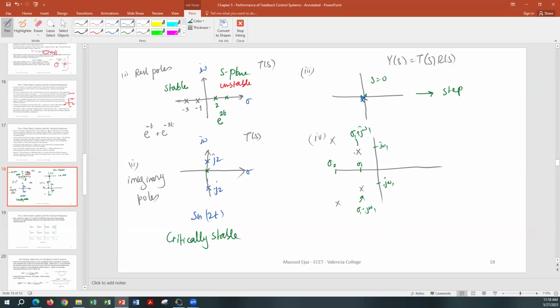As far as the effect of omega is concerned, the higher the value of omega, the more oscillations there are going to be before it dies down, because a higher value means your frequency is higher. So you have more oscillations within one time period. A lower value of omega means fewer oscillations in the response. So you have to look at both the sigma value and the omega value if you have multiple values, and decide which one is going to die faster, which will have more oscillations, and so on.